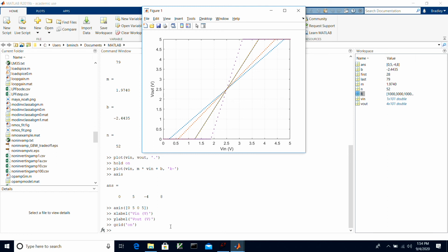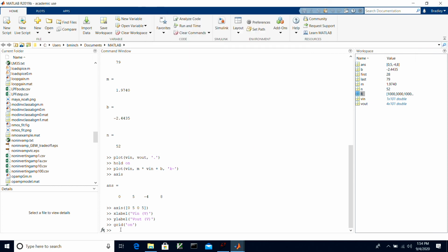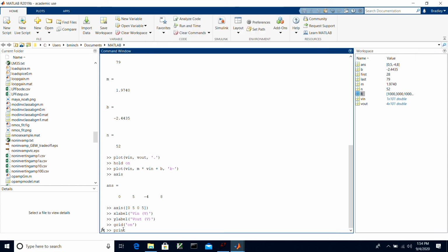And on Windows, a very convenient one, it turns out, is the enhanced Windows meta file. And so I want to just show you how to generate an enhanced Windows meta file from a Matlab plot, and also from LTspice how to generate a schematic as an enhanced meta file. So what we would do is to use the print command. So print, if you do help print,